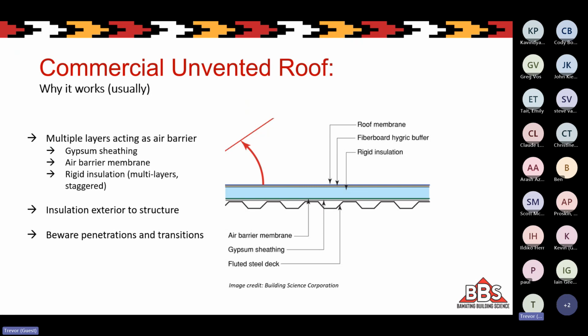So in this case, this is non-permeable insulation, right? This isn't fiberglass. This is rigid foam. So we already have our air barrier that's continuous. We have a continuous layer of insulation, and then our continuous water protection layer. This works really well, especially in just a flat situation like this. This same approach can be used on the slope, which I'll show you in a bit.